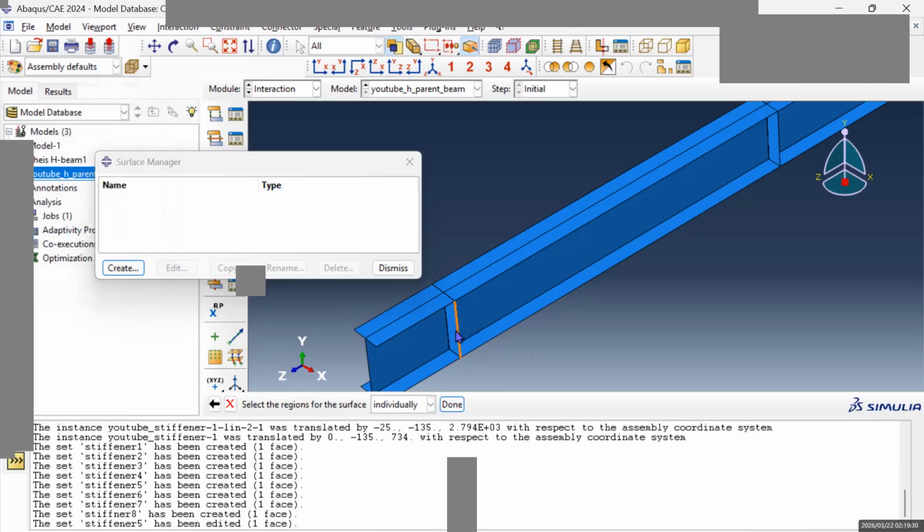So this stiffener here is connected. I'm gonna click on this first. Okay, it should be surface. Surface means you can only pick surface, right? You can't pick edge, you can't pick nodes, nothing. I'm gonna press shift after selecting one surface. It's also linked to this. Okay, let me start for you guys.